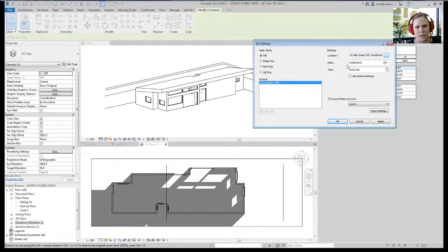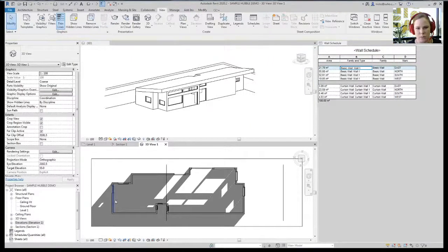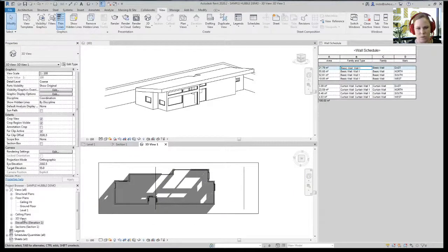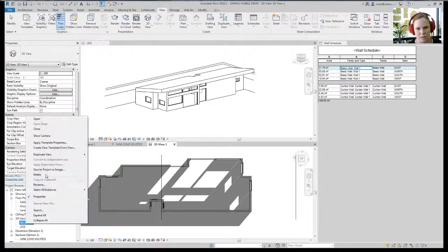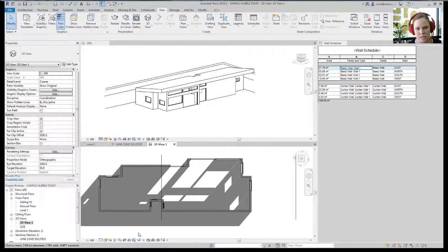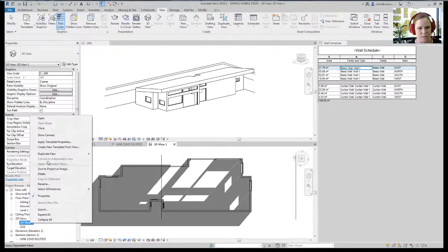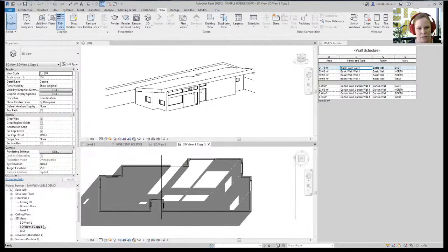The reason I show you that is because one thing is using Hubble, but it's also the integration into your design process and making things more sustainable. So this is a really easy way of checking how much daylighting you're getting into the building. In this instance we did this right at the beginning so we could see how much daylighting gets towards the back of the floor plate, and therefore we know that we don't need as much artificial lighting in this space. Okay, so that was June.